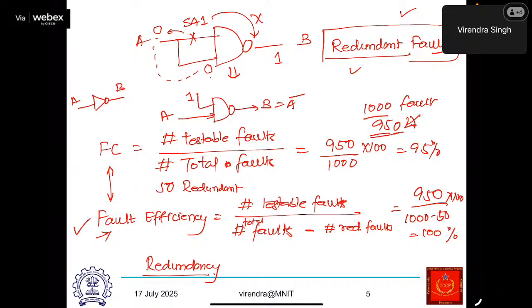However, mostly we develop the 8-bit adder as 8 full adders, because then I can make a cell for one full adder and replicate it. VLSI likes to have regularity, and this provides the regularity. One of the half adders is unnecessarily a full adder, and that brings in the redundancy.